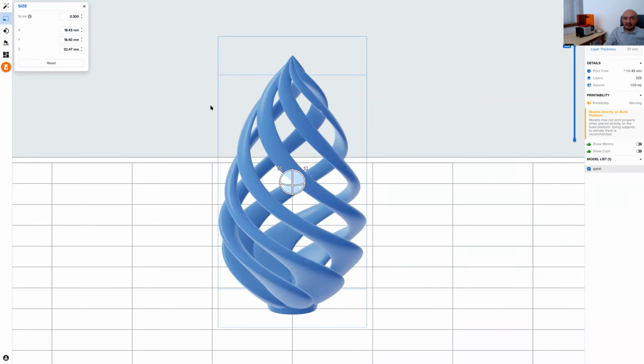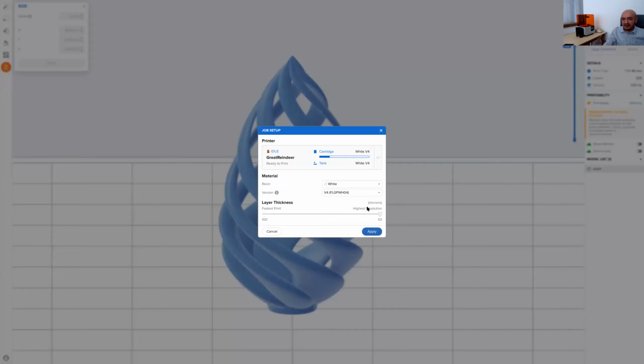0.1. And in SLA, in this printer, we can decrease it to 50 micrometers, which is actually much better than FFF, since if you remember, in Cura, we have in minimum about 60 micrometers, and this is not actually usually preferred. We prefer to have in minimum usually around 100 micrometers, but since in SLA we can print small products, small features easily, you can set it to 50 micrometers and do your print.